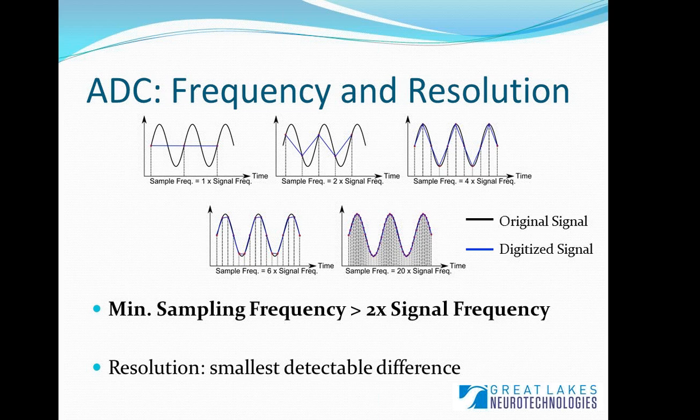In a case where you may need very high fidelity in your signal, such as analyzing and comparing differences in the QRS complex of an electrocardiogram, you would want to make sure that your system can handle very high sampling frequency, so that you get a very high fidelity signal.